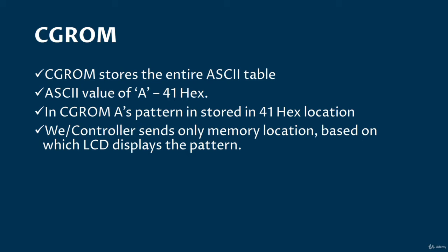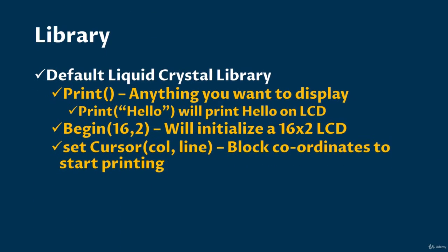CGROM then returns a pattern which looks like capital A, and in the process, A gets printed on the LCD. All these processes are written in Arduino's LiquidCrystal library.